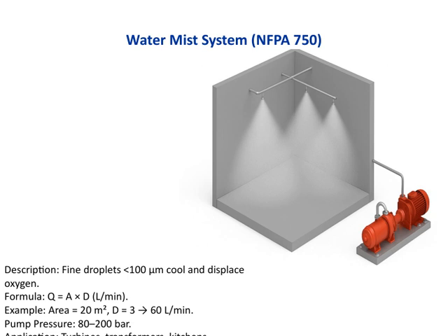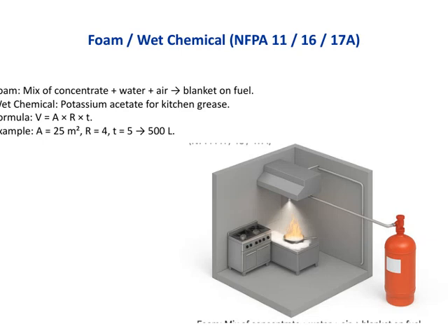Overall, the water mist system is a highly efficient and targeted fire suppression method that leverages fine water droplets to quickly control fires while minimizing water damage. Let's take a closer look at foam and wet chemical systems, referencing NFPA standards 11, 16, and 17A.